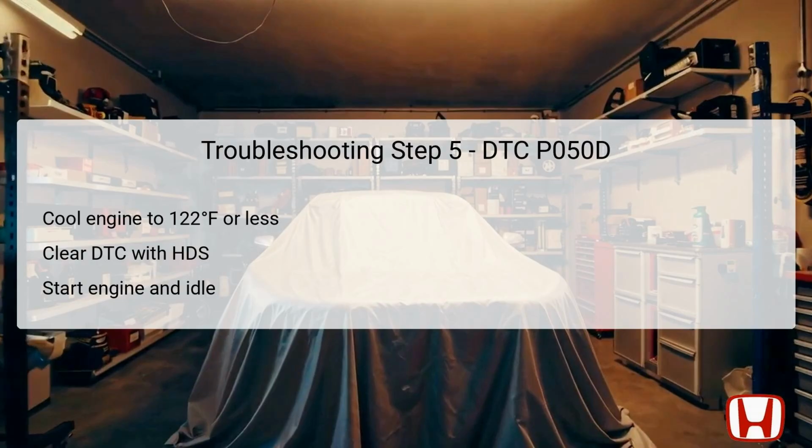After the engine has cooled, it is crucial to clear the DTC using the HDS. Then, you will start the engine and let it idle for at least 10 seconds. During this idling period, it's essential to monitor the OBD status for DTC P050D through the DTCs menu on the HDS. If the HDS indicates failed, this suggests that the original failure has been duplicated, guiding you to the next step in the diagnostic process.